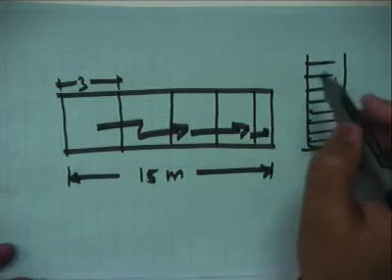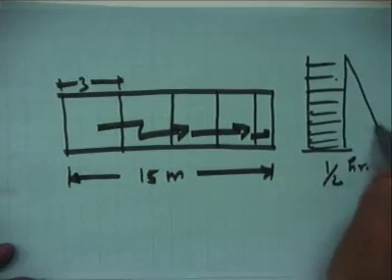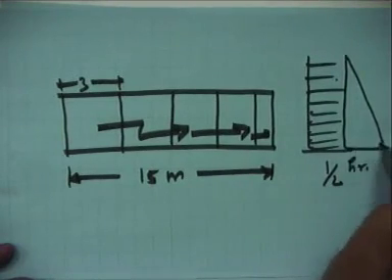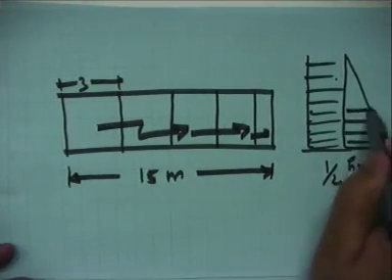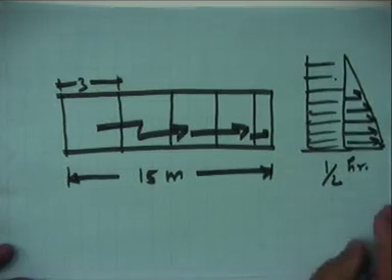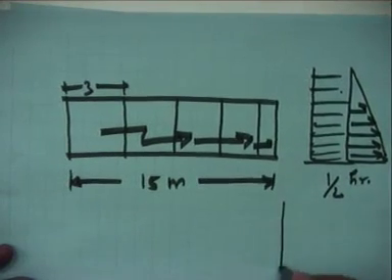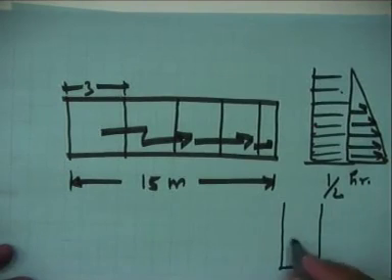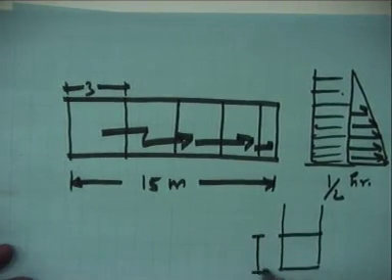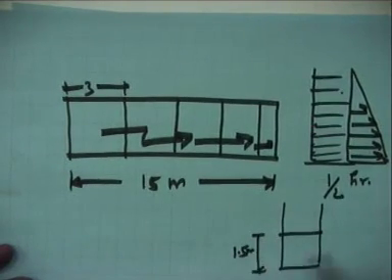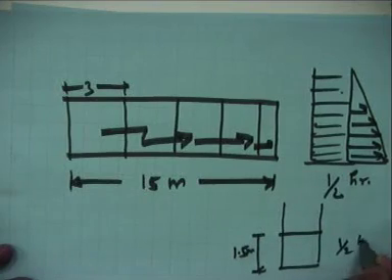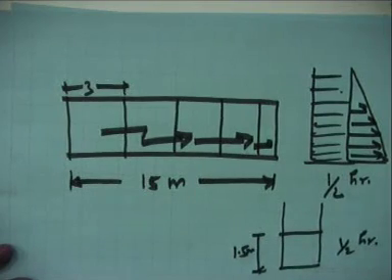Now this will have a different pressure compared to a scheme in which you say that you are going to pour only, let's say, half of it, maybe only 1.5 meter in, let's say, half hour. So that's why I told you the sequence will impact your loading pattern.